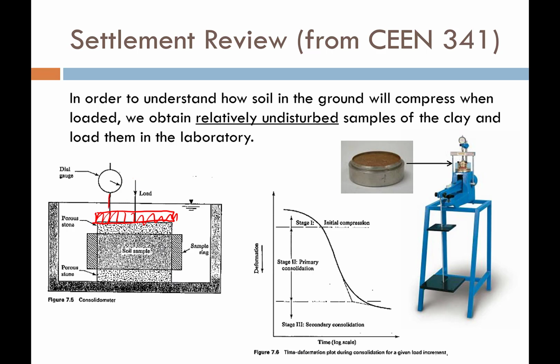On top of that piston, we have a little LVDT, which just measures the strain or the displacement that's occurring, and it measures it very, very accurately. And so we can watch how the soil deforms as we change the load on our soil sample. So what we measure with that LVDT is the deformation with time once we apply a load. We can apply our load, and as time passes, we watch as the soil slowly starts to compress.